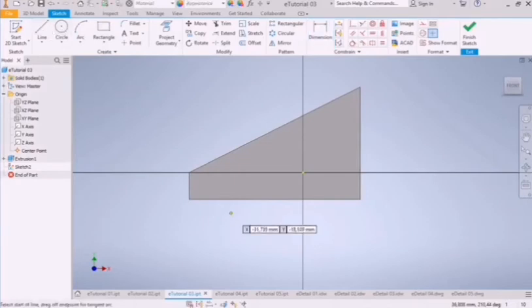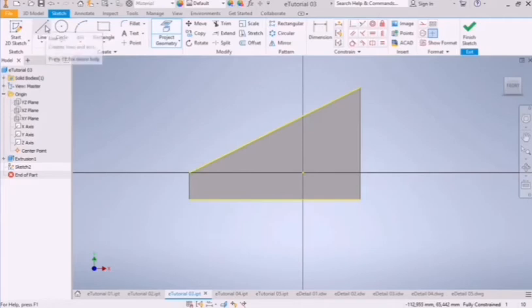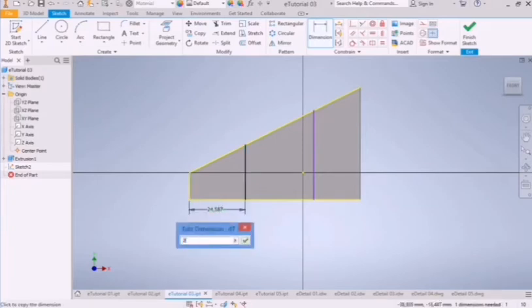Then let's just project geometry there from this line and this line, and then we just draw lines and then just chop off or cut off what we will need from there, the geometry to this one, again from this geometry to this bottom one, and then let's dimension them as specified. This is 25, and as well this is 25.